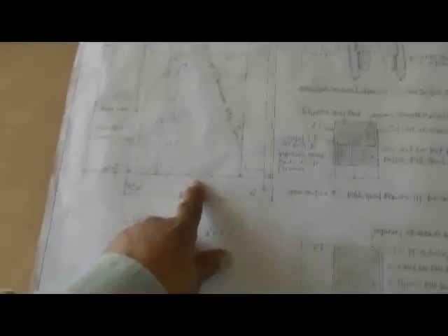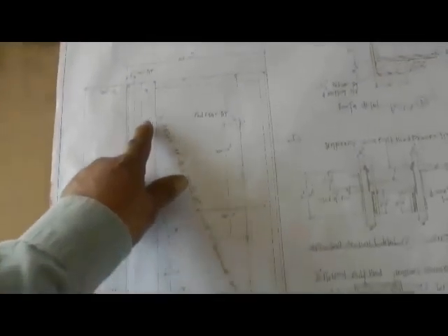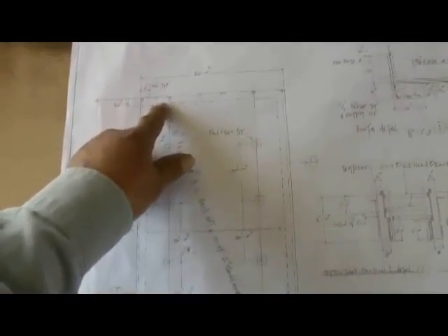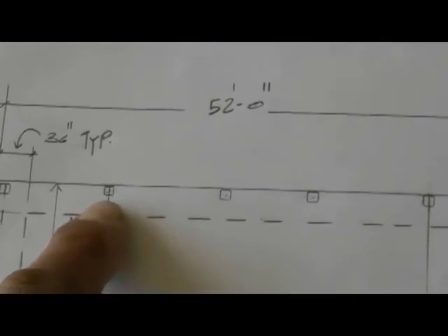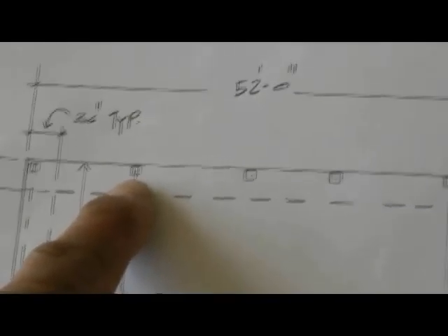Where my finger is, if I go to my right now, and I go to this corner here, this is the east end of the building. There's the door, the main entry right there, okay? Now, I'm going to go to this grid here, and that grid line is called B, grid line B, and I'm going to jump another area, and that's grid line A. Now, if I follow that grid line A all the way up to the west end of the building, I'm going to find right there, I'm going to zoom in now, that little square thing, it's not noted here, but it is going to be noted later.